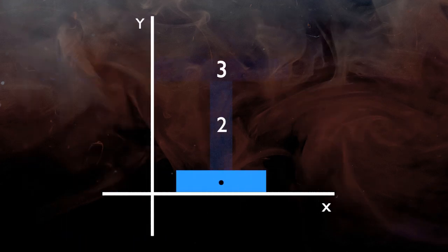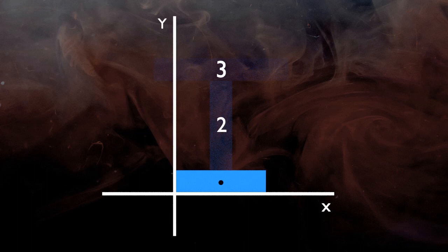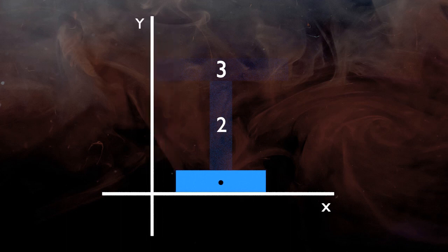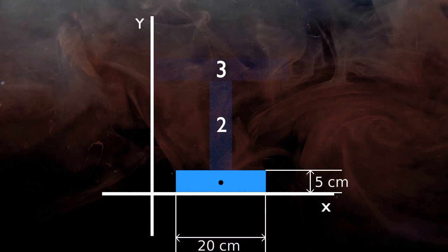But this method can be applied only if the reference axis is placed at this location. But it is not the case. The location of the y-axis is some distance away from rectangle 1. So a little change in coordinates will be necessary. To find the x coordinate, we have to add this distance from the reference axis to the previously found coordinates of the shape.